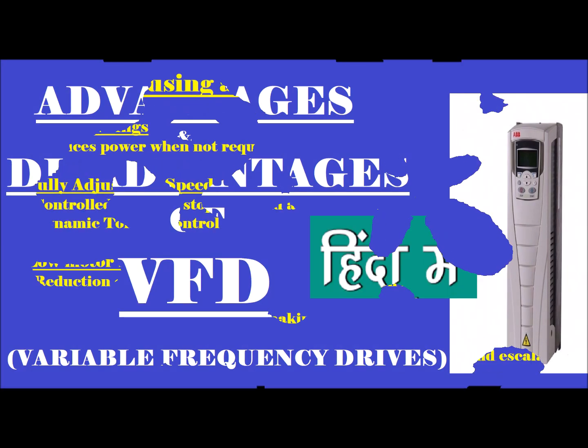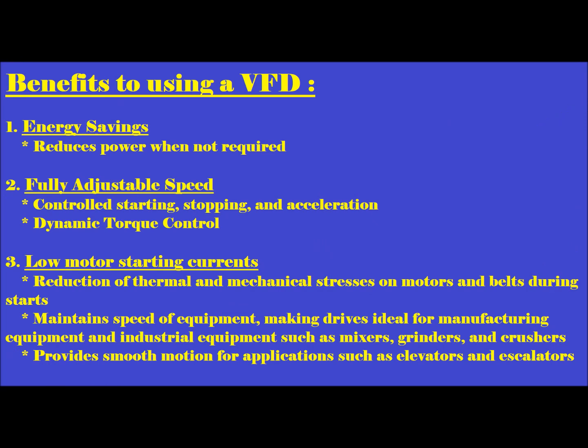So without ado, let's get started. In brief, we will first see the benefits or advantages of using a VFD. There are 3 points and we'll go into detail later in the video. The first point is energy saving, that is, the consumption of power reduces when there is no requirement. When the load increases, the VFD will use more power, and when there is no load or less load, the VFD will consume less power.